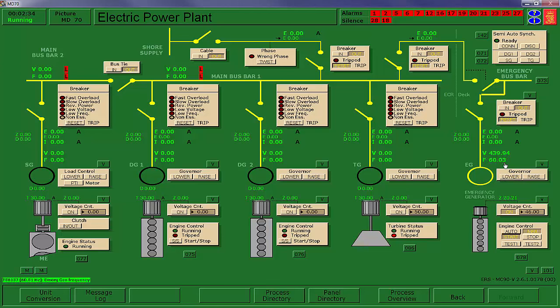So what you're going to be doing when you're testing, and as you practice, is leave this field on one of your monitors, and as you initially load up this generator by starting motors and that type of thing, you're going to watch this frequency and raise the governor up as needed. I'm not going to do it because I want to have a negative indicator on our assessment so I can show you that and we can talk about it a little bit. But again, when you are running this, you need to regulate your frequency and keep it steady.